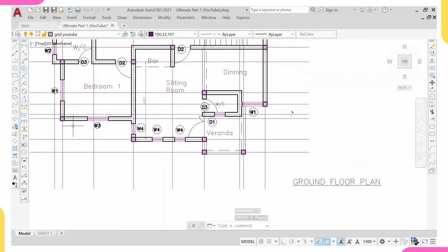But another engineer can decide to leave it. It is dependent on the engineer. But me, I don't want to leave it. I want to remove it. To save cost, because this is 4.4 meters and I said it should not be more than 6 meters, 4.4 meters is too small. It will be able to carry the load coming from this side and from this side, and also this point load. So to save cost, I will remove this column.